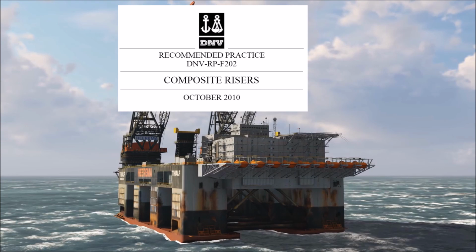Generally, you don't use composites directly. You will always have some kind of reinforcement which is metallic in nature, and again, people have to look into that. There are always certification societies, so whatever you are designing, you always have to get it certified against different standards and design codes, and DNV is one of them. For composite risers in subsea operations, you can find the DNV document DNV RP F202, which discusses composite risers in the subsea environment.